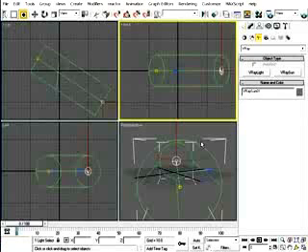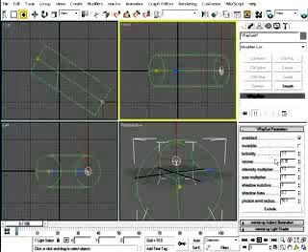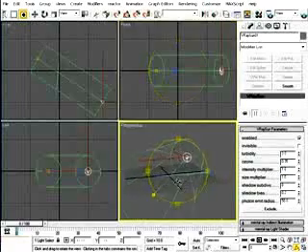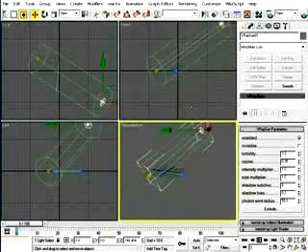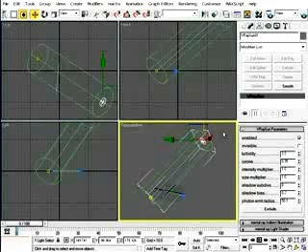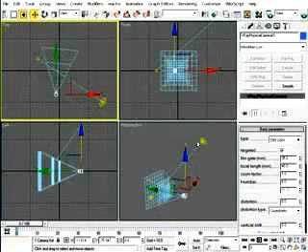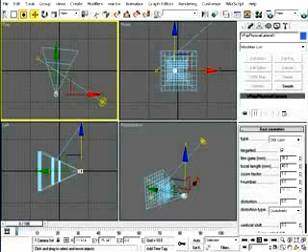One more note about real-world results. The VRay Sun multiplier, which is set to 1.0 by default, provides far too much illumination for most scenes when a standard camera is used, unless its intensity is offset in other ways, such as color mapping. But when you use the VRay physical camera, the VRay Sun multiplier of 1.0 is designed to yield real-world lighting. So the bottom line is, with a VRay physical camera, you can't expect to get real-world results in your renderings if you use abnormal skylight, abnormal primary bounce multipliers, and so on.